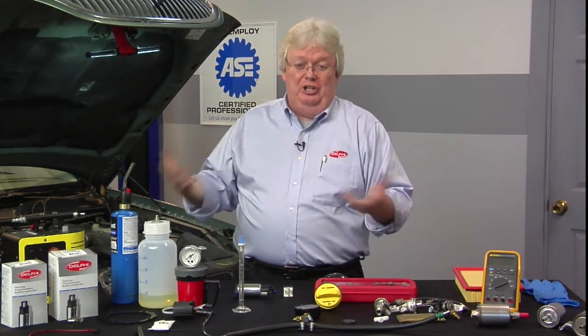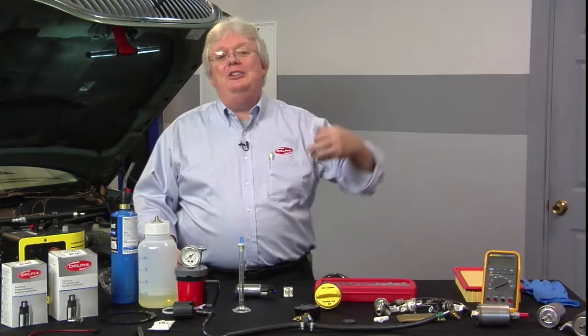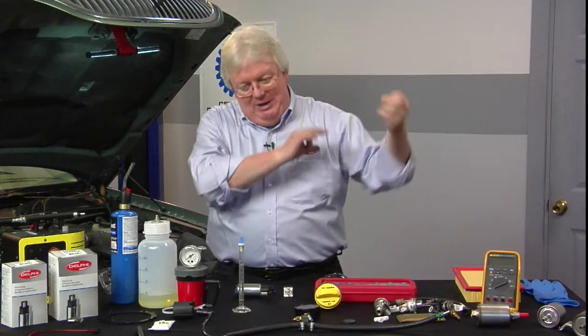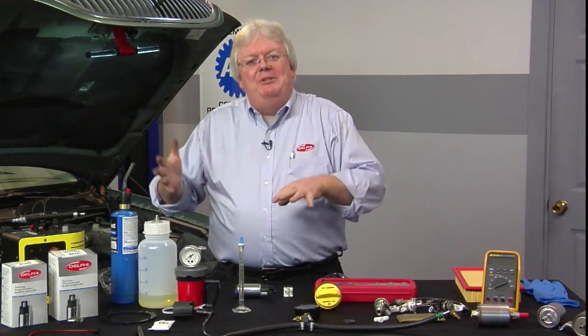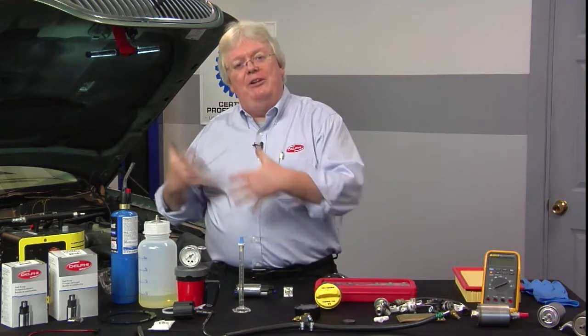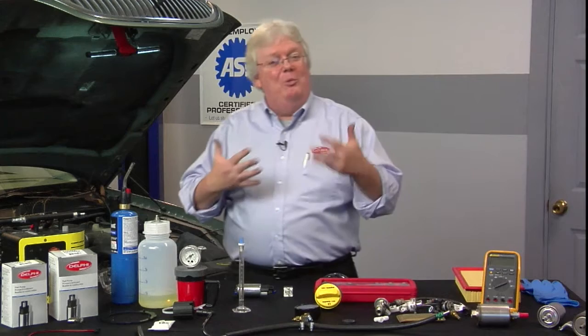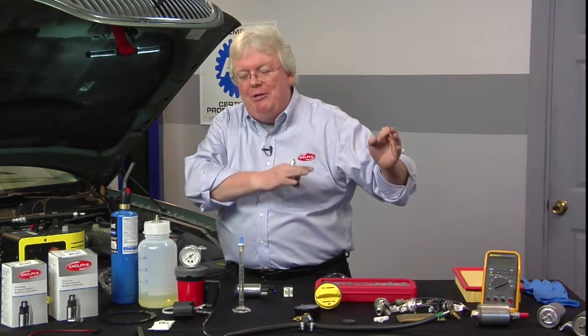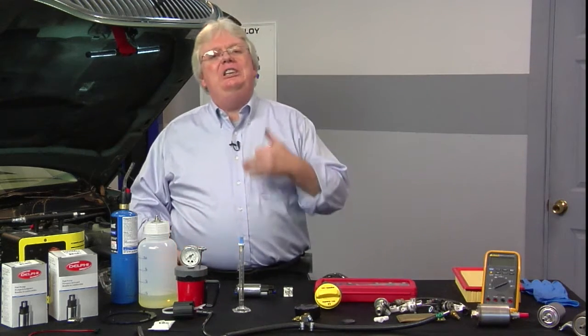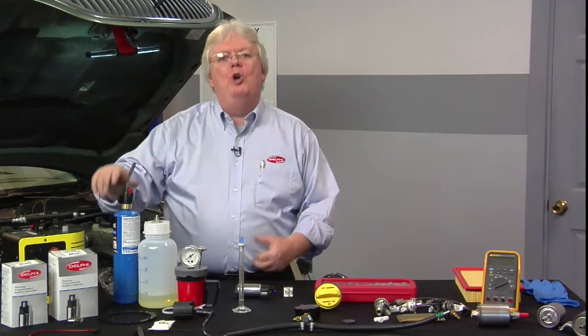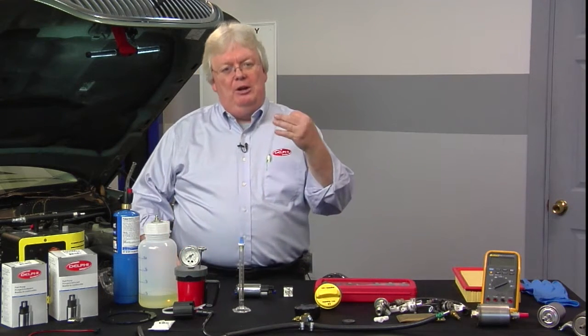So sometimes it's hard to determine which comes first, the chicken or the egg. Is it an O2 not responsive and we have trim numbers trying to compensate because we're not doing a good job of air fuel management, or is it an air fuel management issue to start with and the O2s are properly reporting that information? So if you see lean, you make it go rich with a propane or some other source to make her go rich.